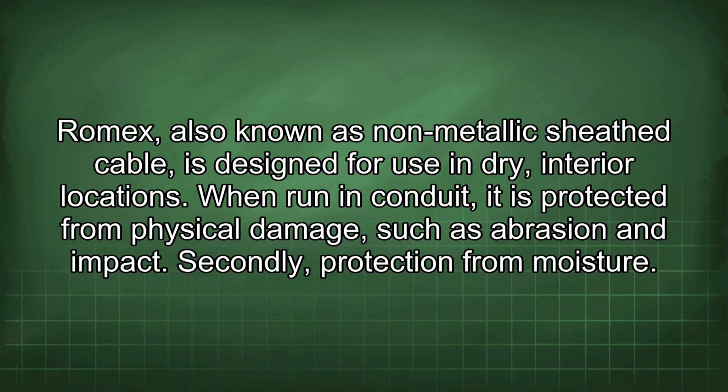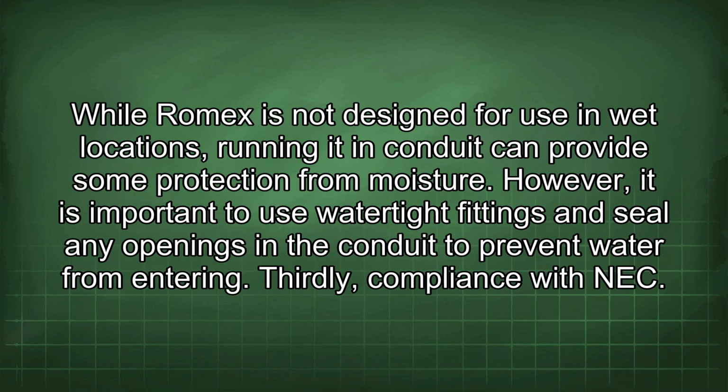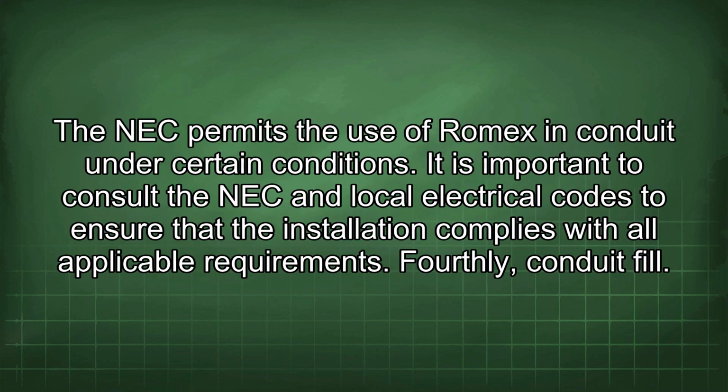Secondly, protection from moisture. While Romex is not designed for use in wet locations, running it in conduit can provide some protection from moisture. However, it is important to use watertight fittings and seal any openings in the conduit to prevent water from entering. Thirdly, compliance with NEC. The NEC permits the use of Romex in conduit under certain conditions. It is important to consult the NEC and local electrical codes to ensure that the installation complies with all applicable requirements.